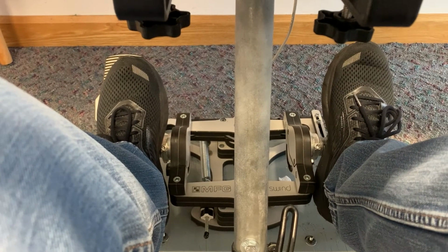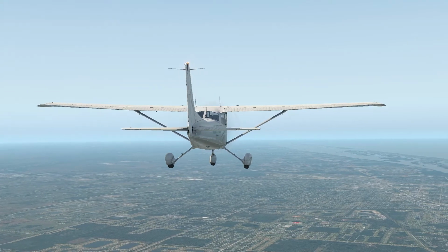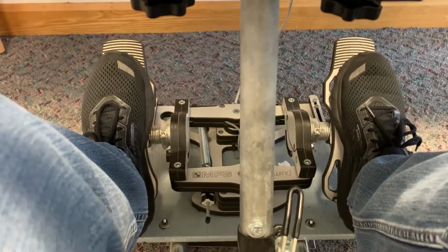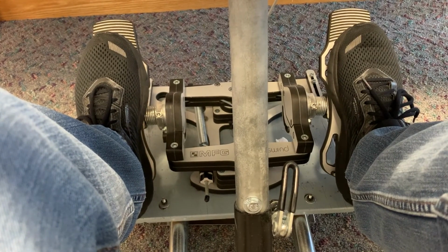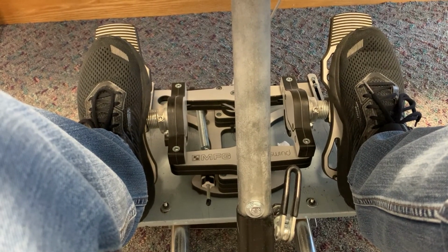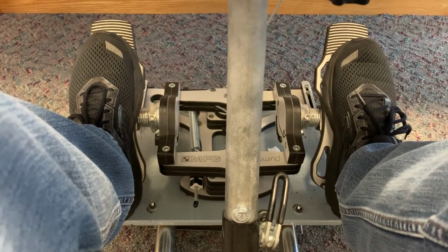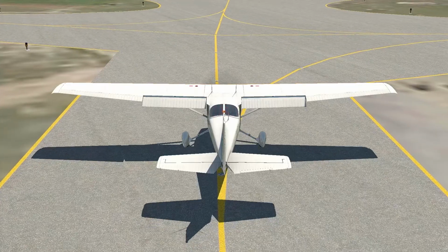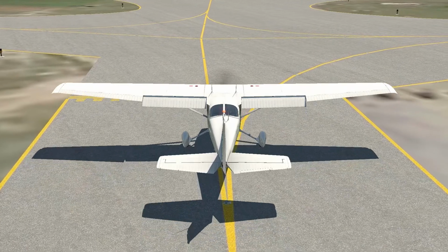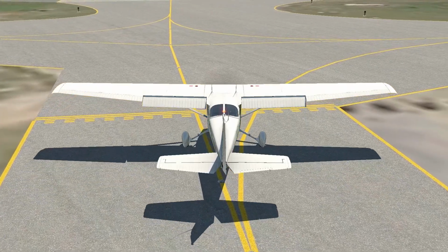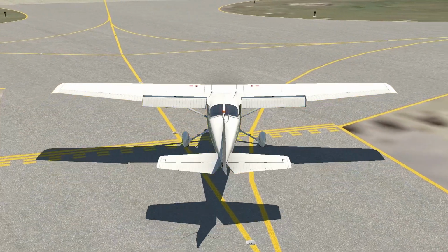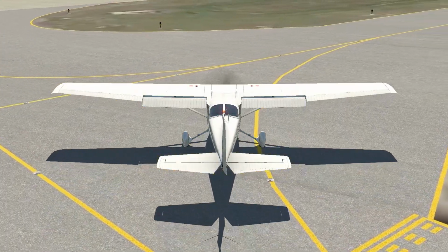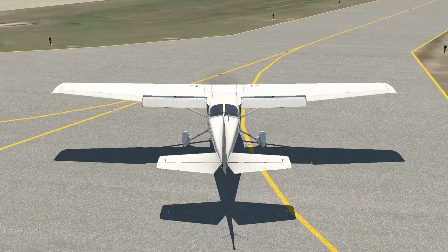Rudder pedals control the rudder, a control surface used to keep the airplane in a coordinated, comfortable turn. Using slight pressure in the direction of your turn will help the airplane turn properly, relieving any centrifugal forces you would experience in a real airplane. While taxiing on the ground, the rudder pedals are used for steering in most aircraft. Push the rudder pedals in the direction you want to steer, but do it slowly and gently to avoid a ground loop or spinning in circles on the ground.